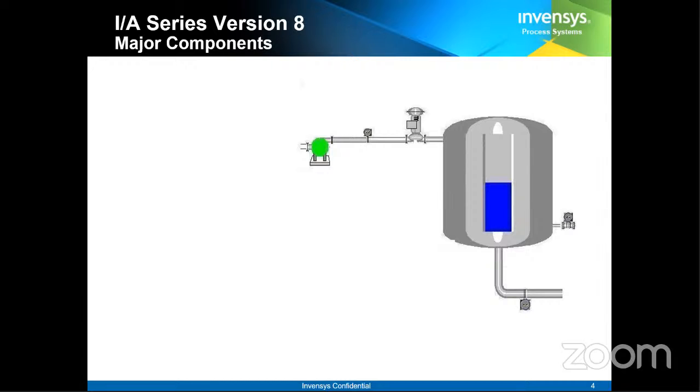In a continuous control loop, the most common thing we use is a PID application, where we have proportional, integral, and derivative, these three different controllers. So in this particular example, how can we achieve this continuous control to maintain the level in this tank? That is my intention over here.